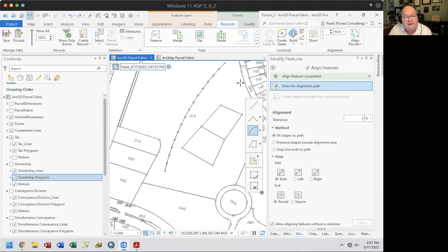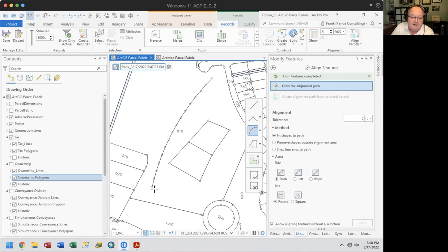The problem with that is that there's rounding errors associated with that. If you have a long curvilinear road, by the time you get to the end, you might be 2-3 feet off because of the little rounding errors that occur. Yep. So for right now, I would say, okay, you've got 2 suggestions. One is build the smaller ones. And as you're doing that, make sure that if you're doing it within a traverse, you close the traverse out on where you think it's supposed to be at the end.